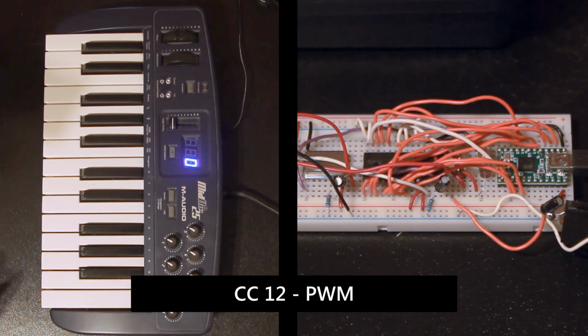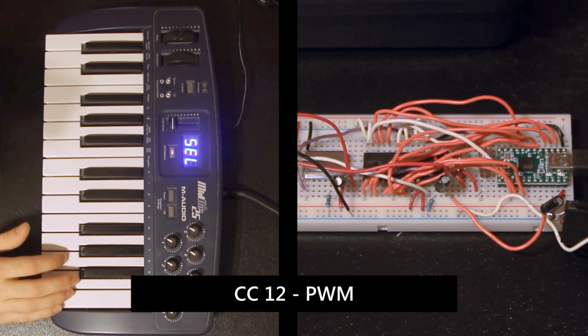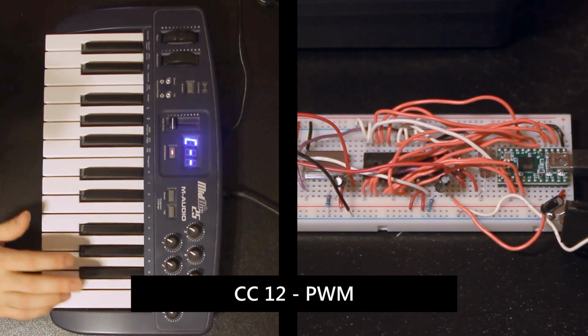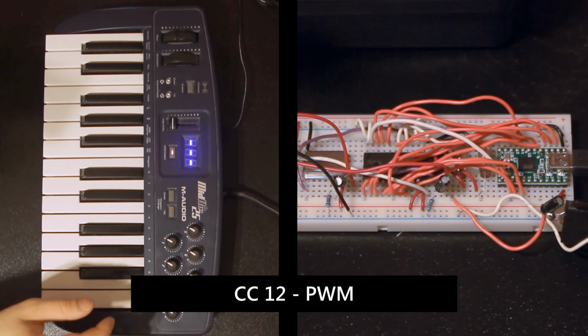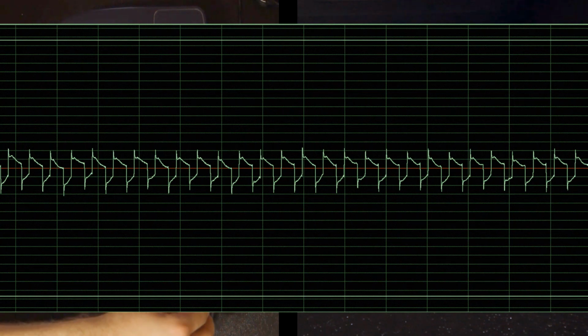A signature feature of this chip is the ability to modulate the pulse width of the square waveform with 12 bits of resolution. So you can either set a duty cycle or you can sweep through the range, which gives the effect of putting a phase shifter on the sound, which gives the sound some movement and life. This is assigned to CC12.